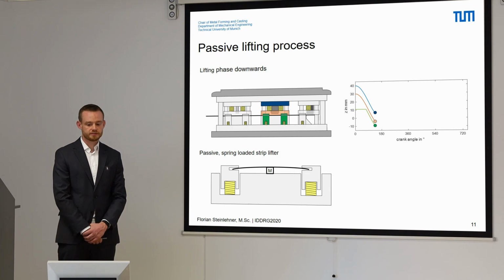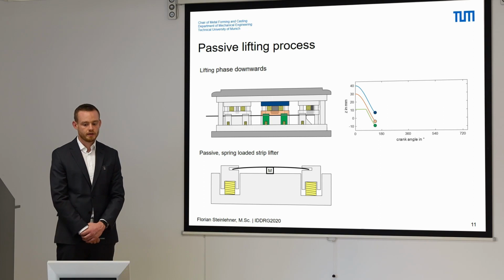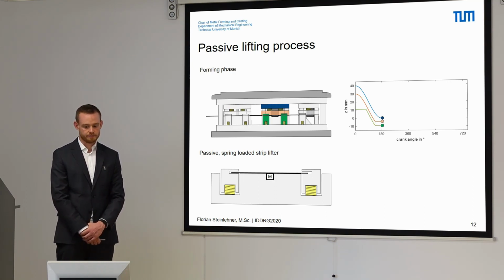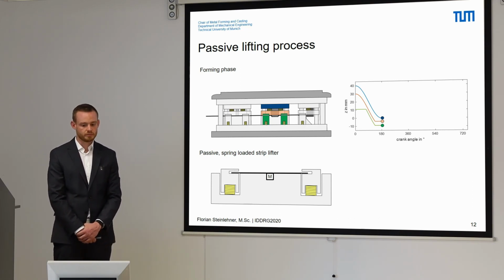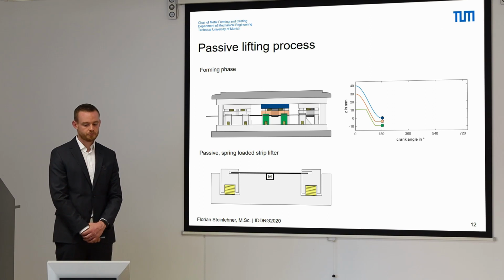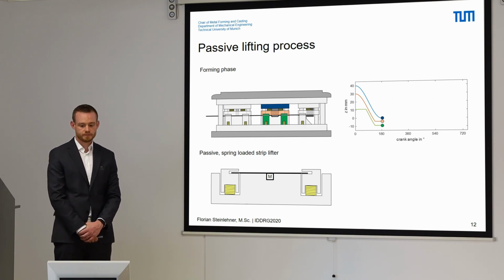The strip lifter is then pushed downwards while the middle part of the strip is following with a delay, and its spring is compressed until it reaches the level of the die and the strip becomes clamped between the binder and the die. After the strip is clamped in its designated position, the forming and piercing punches come into action. Every possible impact or vibration resulting from those forming operations will not affect the strip, and is stamped and gone until the binder releases the strip.